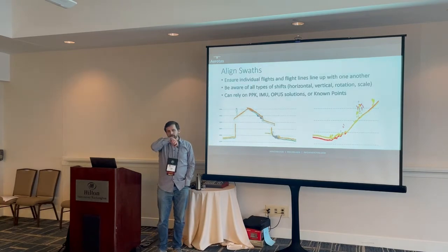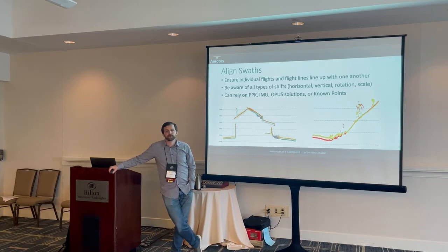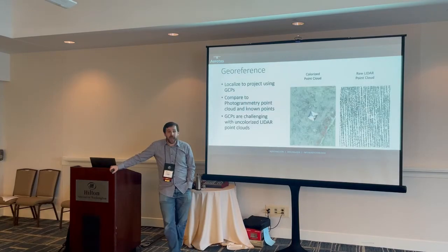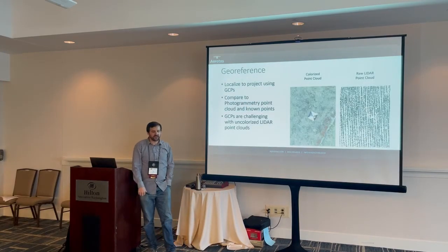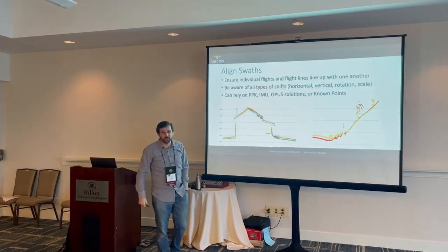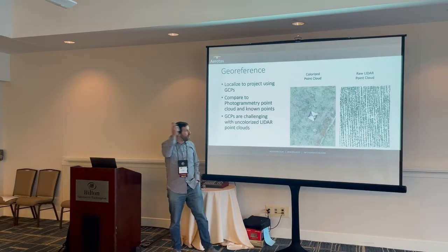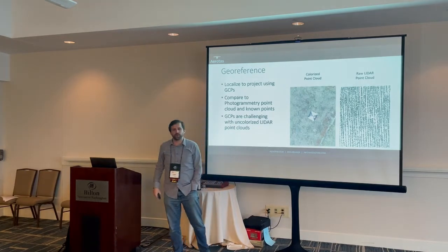Do you ever reinforce your Opus solutions with your local GPS, your survey grade GPS? Because you probably do a base station setup and your flight Opus rapid static is 15 minutes. So, that's not a great solution. Yeah, so absolutely yes. We do all of that to get that single precise point cloud, not your final point cloud. Because your final point cloud, you want it localized to the site. So we will always trust ground control over our Opus solution.